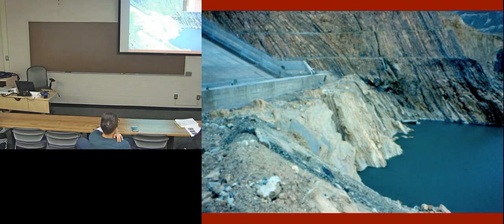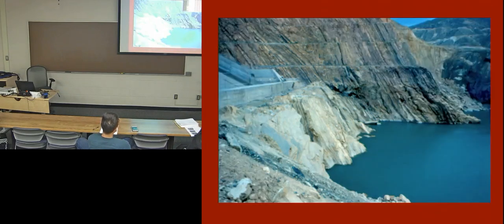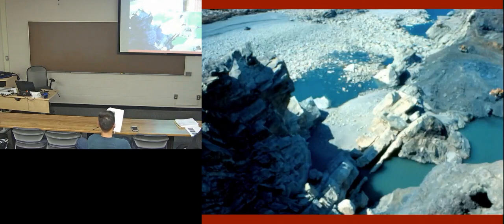But anyway, nobody recognized that there was a fairly large, dark rock dike, an intrusive dike, just downstream of this plunge pool. And there is that dark rock. And you see it over here. Here it's been partially excavated, because we've got to get rid of it. We want this plunge pool to go out into the channel of the river.